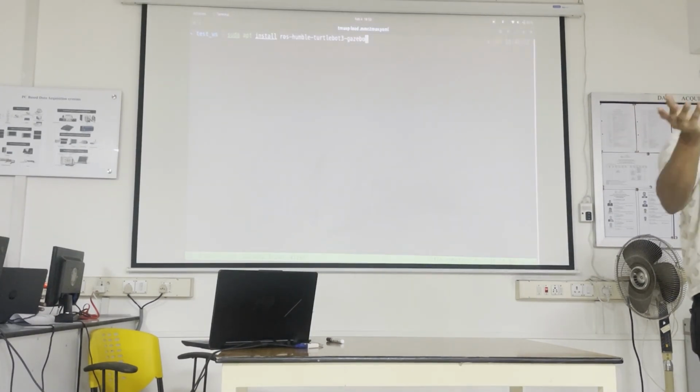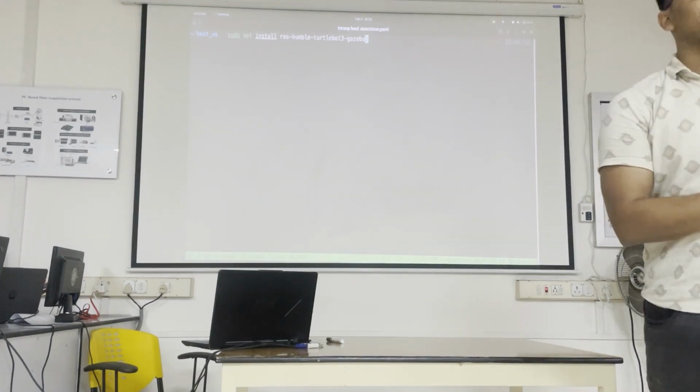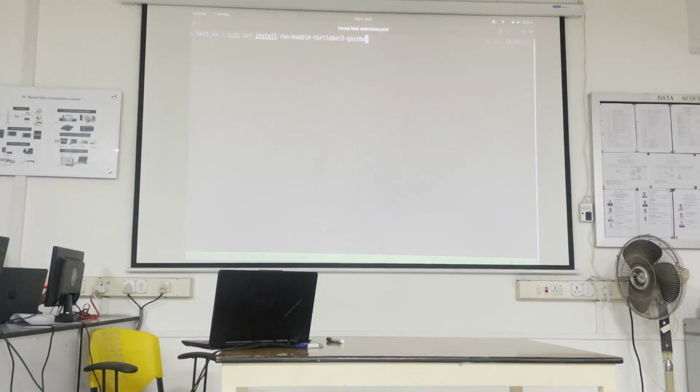You can put objects, play around with things. If you want to control a bot moving in Gazebo, you can use ROS to communicate with it. ROS is a communication framework and you have an API to make use of ROS. Same thing with Gazebo, you have an API to make use of Gazebo. These guys have already written that. You don't have to do that stuff.